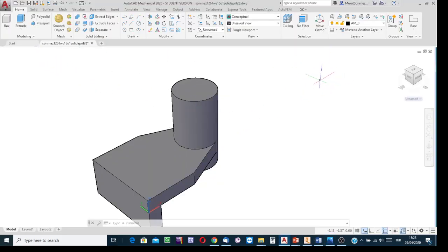Of course, you can create a cylinder in the vicinity of, at the outside of the existing one, and then move the cylinder to here and then apply subtraction. Or, since I know that it uses the center of the edge of the cylinder, start the circle creation process in diameter mode, and then bring the cursor to the vicinity of the edge of this cylinder.